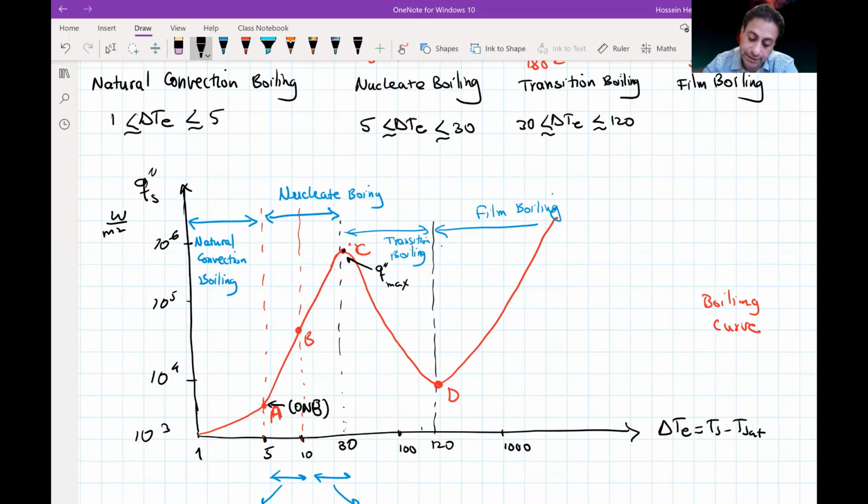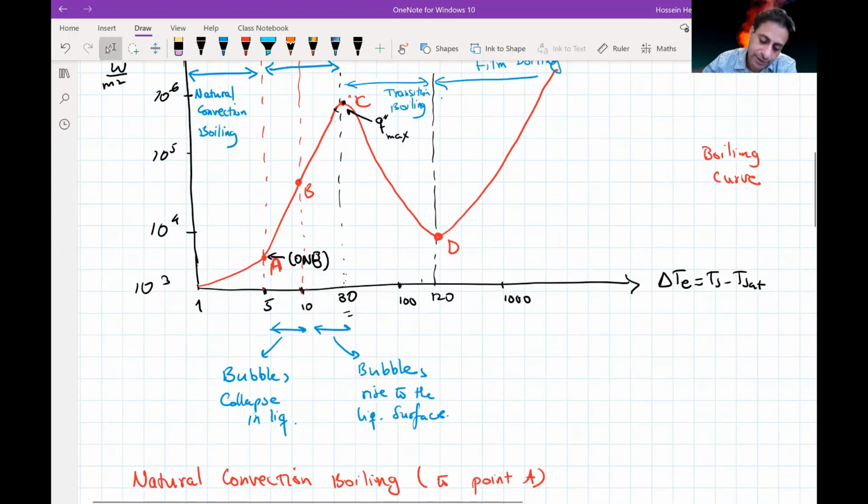The more heat we deliver, the more vaporization and the stronger the rate of vapor formation. In nucleate boiling we can reach close to the maximum. We are going to avoid the maximum point, which I will explain later, with a small surface temperature, about 30 degrees C.